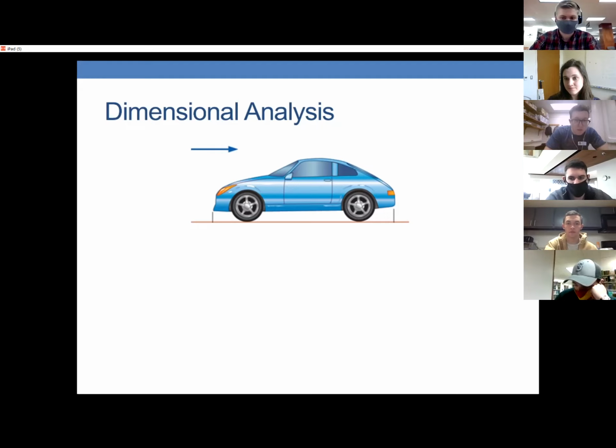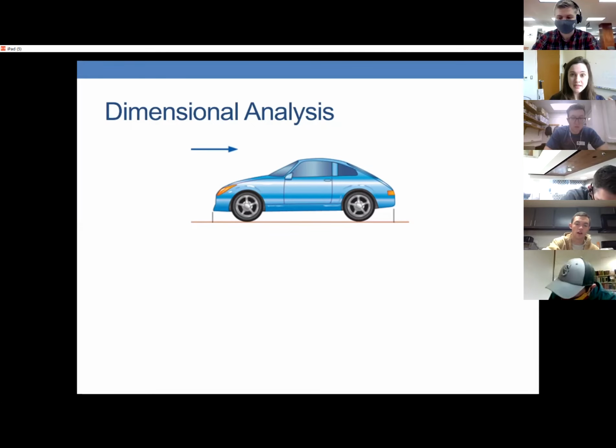It could help you save mileage. Yes, the lower the drag force is, the better your mileage will be, because that means the less force you need to generate in order to go forward and push against all of that air that is pushing back on your car. So we are very interested in knowing what the drag force on a car is.